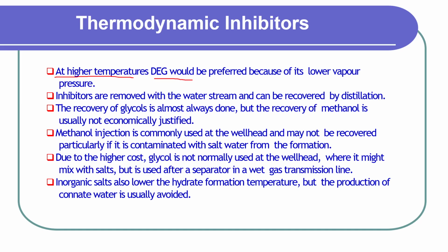You can conduct distillation, where you separate the water away from, for example, the glycol. But in the case of methanol, it's very hard to do. For glycol, you can do the distillation, or recovery of the glycol from the water stream after the injection. But in the case of methanol, it's not really economically viable to do the separation.